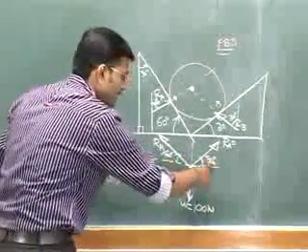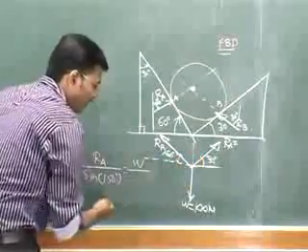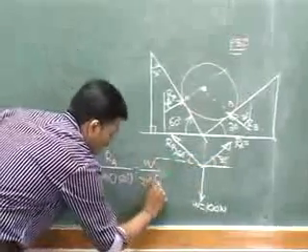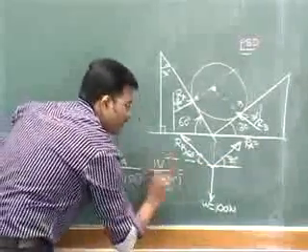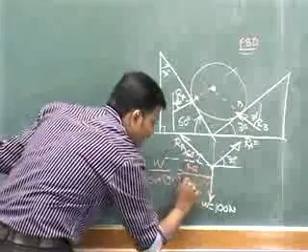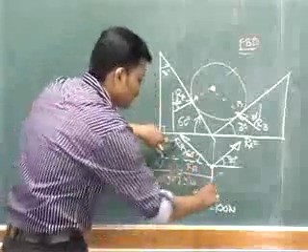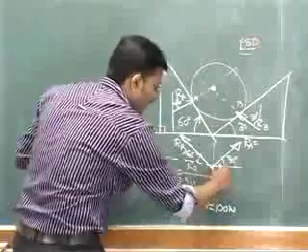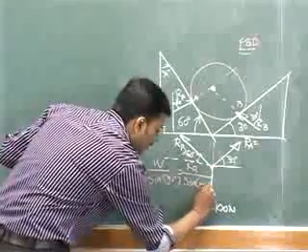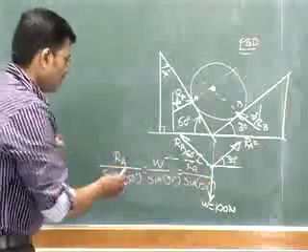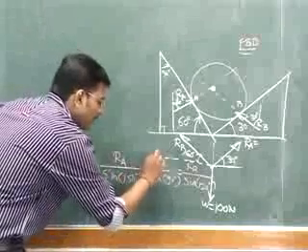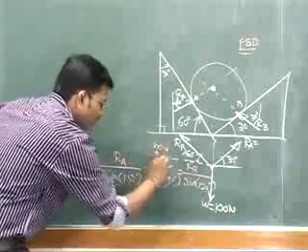So 60 plus 30 is 90, total is 180, so sine of 90 degrees is equal to RB divided by sine of... when you are taking this force, the angle between these two is important. So 90 plus 30 is 120 degrees. So W is known, W is nothing but weight component, it is 100 Newton.